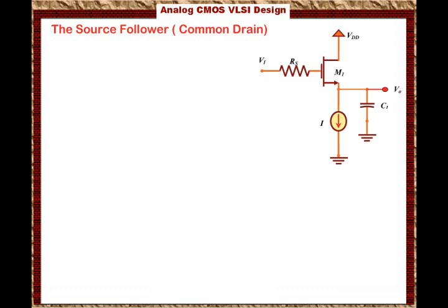So basically, CL is the capacitance, and the electrostatic discharge circuit usually has large capacitance, and that is directly connected to the output pin of the IC chip. So CL is large in value, and it's specified by the technology and the design we use. It is part of the specification of your IC chip.